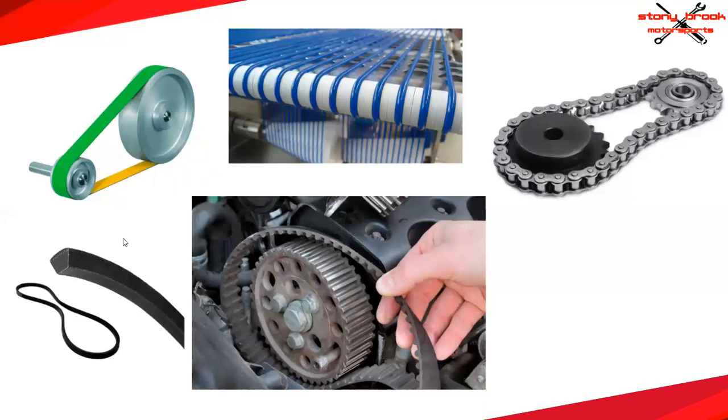The bottom left one is what's called a V belt, and it's shaped like that because it has that V shape, as you can see. This is actually what's used on our CVT. And then you have a timing belt over here, which is a tooth belt, which goes onto a pulley also with teeth. These are nice because you don't transmit power through friction. You actually have power transmission through the force of the pulley onto the belt teeth. We use this on one of our powertrain elements, which is our intermediary belt box.